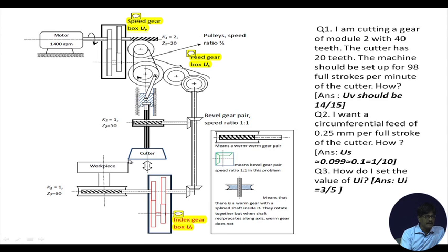But we actually give some relief angle or clearance angle towards the back of the cutter, so that while it's machining, this surface does not interfere with the finished surface formed on the workpiece. As it goes down, it removes material by this side, the rake surface, and the clearance surface is relieved away. This surface, the flank of the cutting teeth, is relieved away from the finished surface, so that there is no unnecessary rubbing.